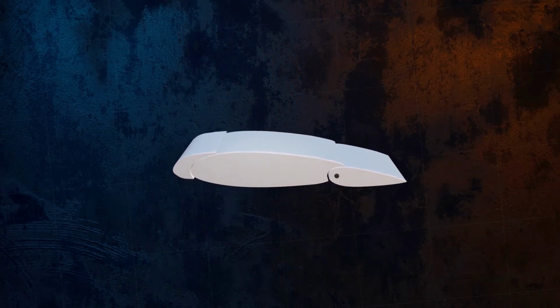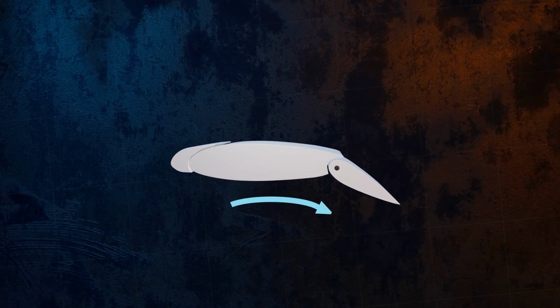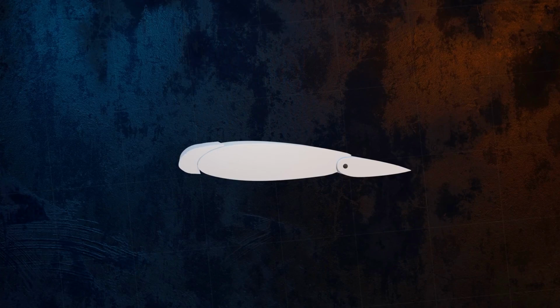During takeoff, for example, you want high lift. Extending the flaps increases the camber of the wing, which increases lift, and so flaps are extended during takeoff. But the extra lift comes at the expense of increased drag, and so the flaps are retracted when cruising, since high lift is no longer needed, and the drag should be minimized to improve fuel consumption.